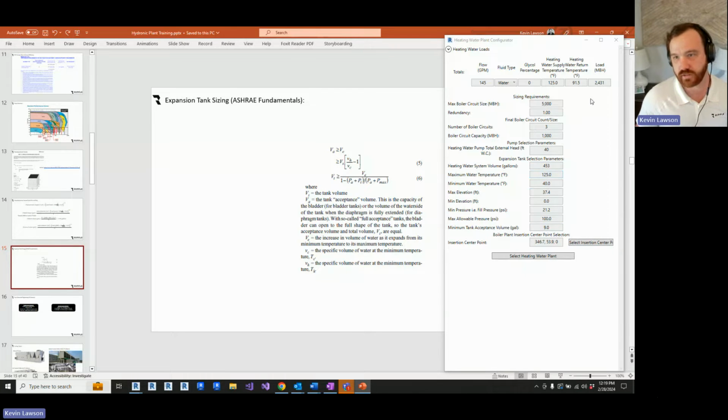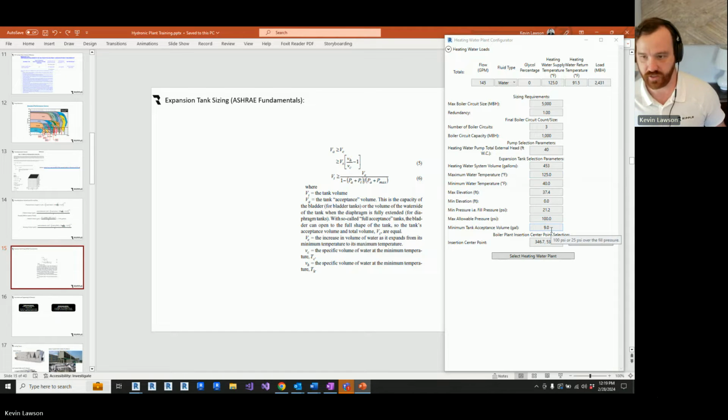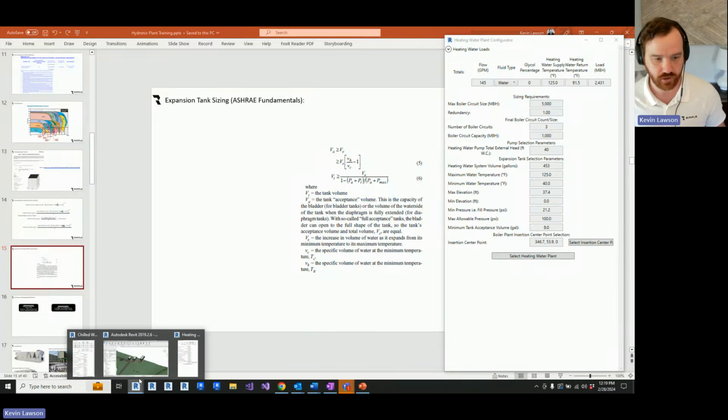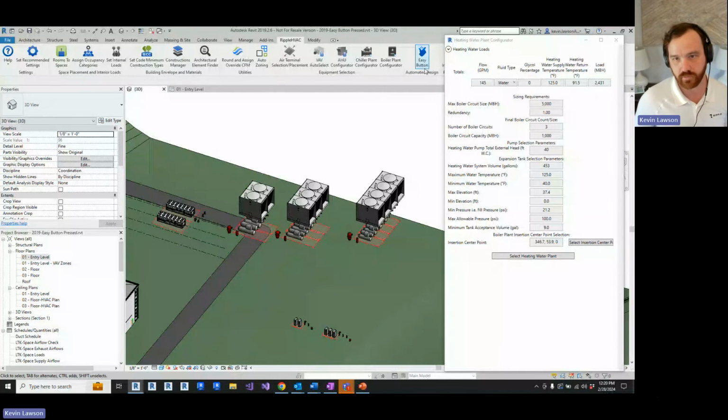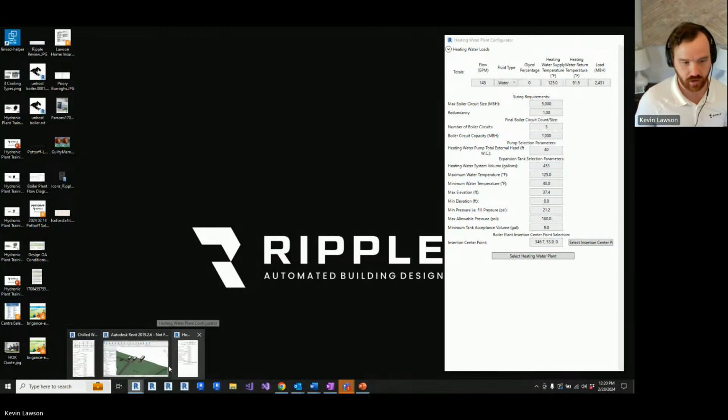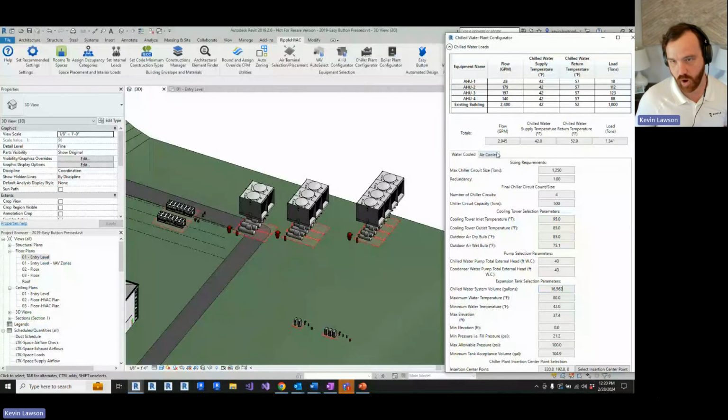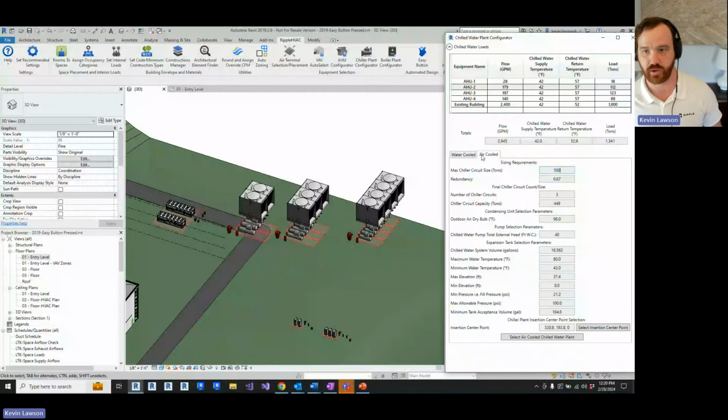So all of these inputs are overridable. It's just that they are going to have default values, and those default values are going to be used when we hit the easy button, or when an architect uses the engineering on demand tool. The default values and default selections, especially for air-cooled or water-cooled, are what we need to dig into a little bit more. So when do we select water-cooled and when do we select air-cooled? We're going to talk about that first.